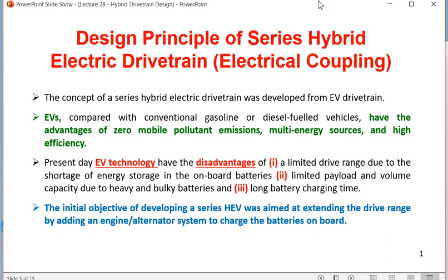One another mode was there, which was the 8th or 9th. At that time we had seen that the primary energy source, that is the engine, was charging the secondary energy source, the battery, and it was not giving any power to the output transmission. So the primary source was charging the secondary source, and the secondary source, that is the battery, is actually driving the whole vehicle. In that case, the amount of emission of pollutants in the air becomes very less.